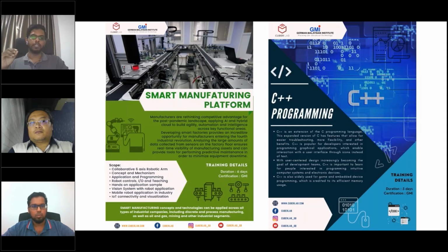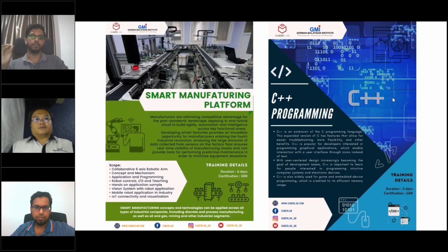Because when you put a vision on the tool itself, there are some advantages and disadvantages. For example, if you want a good cycle time and you mount the vision on the robot, you have to take a picture and process it before you pick the part. But if you put a stationary vision while the robot is moving, another picture is taken and the decision has already been made. So it increases your cycle time output. The decision of what kind of vision application depends on your process, then we make the decision accordingly. And most vision systems are able to do most of the processes.